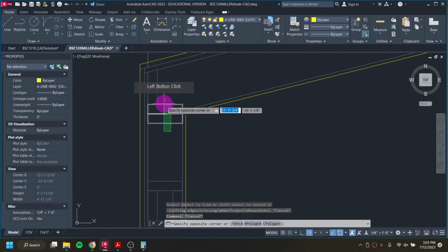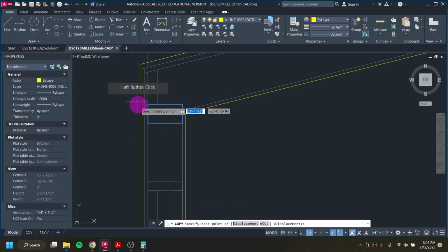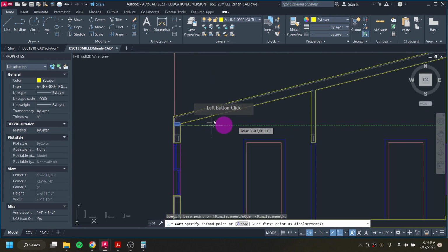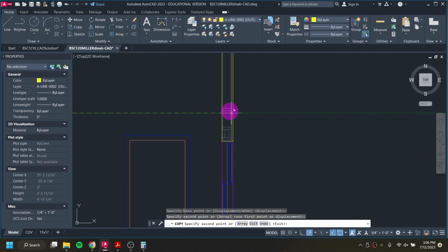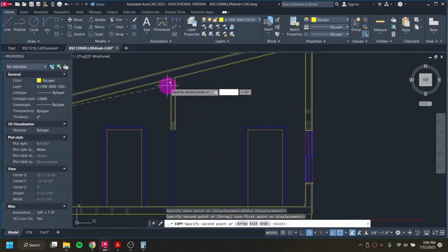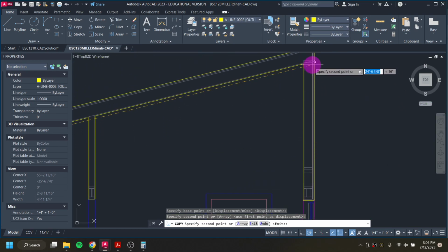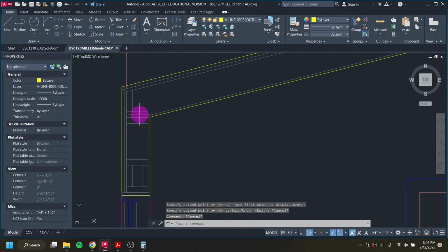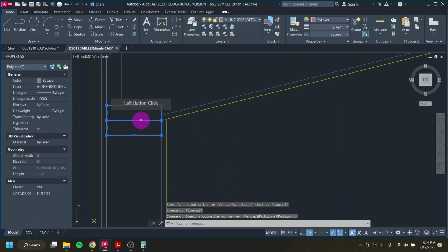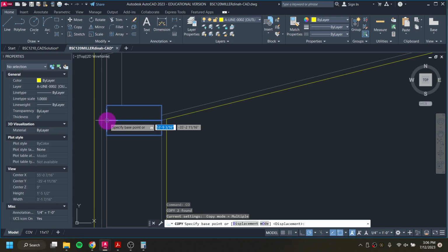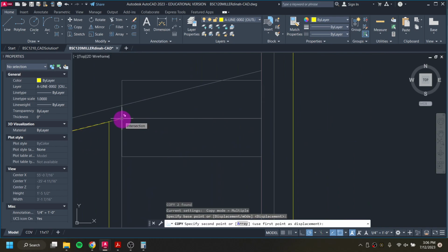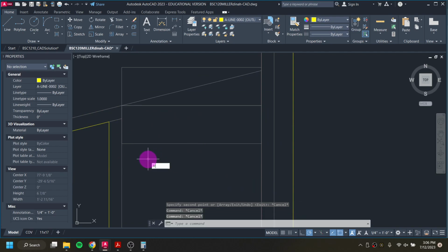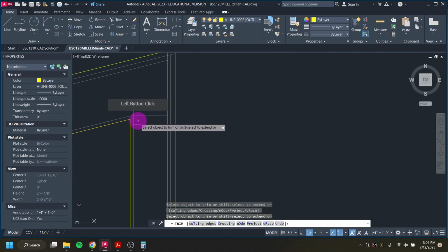And then I'm going to take these two and copy them from this side over to this side, because they're already going to exist over here. And then we'll need to build out another double top plate up here, which we can, if we want to, take these ones, copy, grab them by the middle where they meet, so that way we can put them where they would intersect here. And then TR, enter, to trim that part out.